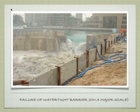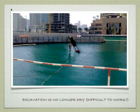So this is that same slurry wall. This wasn't a strong enough wall. It didn't have proper tiebacks. Recognize the tiebacks wouldn't really work over here because you're going into water instead of earth. So this is problematic. Something like this can happen. So this is the canal on the other side of this excavation. You can still see all of the cranes and that kind of stuff, and so you end up with this.